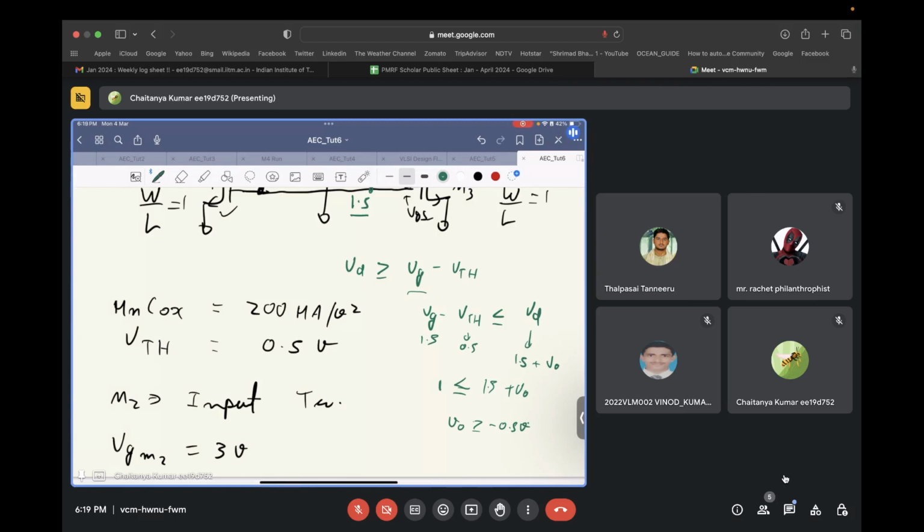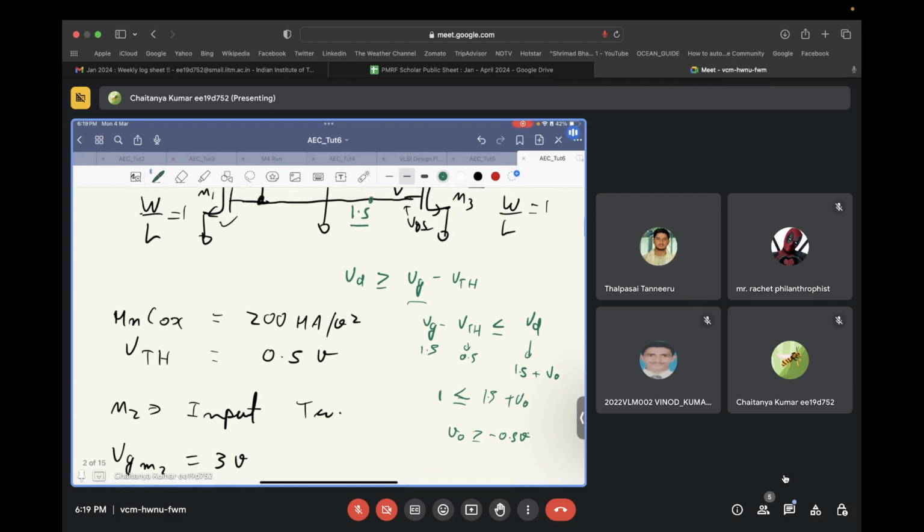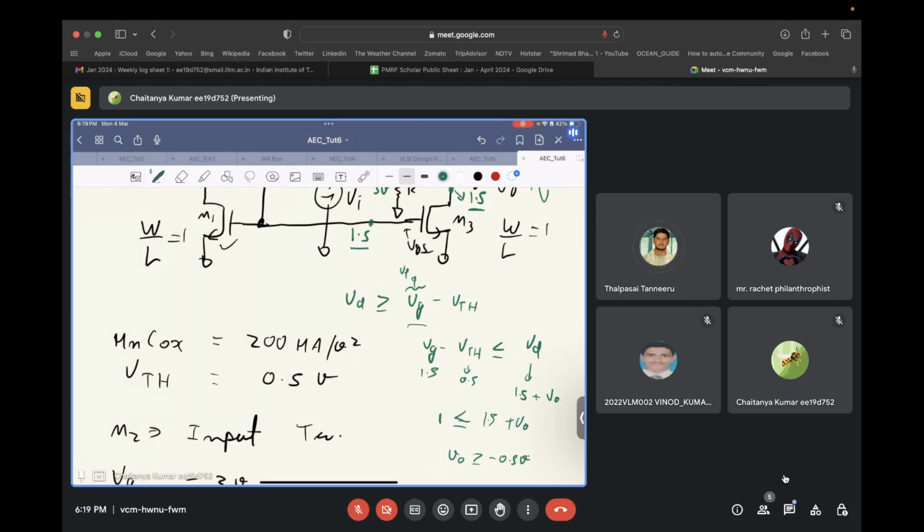Basically, for each transistor that you suspect can go into triode, you have to write that boundary condition of the triode. That will contain the gate voltage of that transistor and the drain voltage of the transistor. Depending on the circuit, if both the gate and the drain voltage are varying with some gain, you will substitute the gate and drain voltage with the fixed voltage that it has, V fixed, plus whatever small signal voltage, V small, is riding on top of that. You will substitute it in this boundary condition, and from there you will find out what constraint is present on the input voltage.